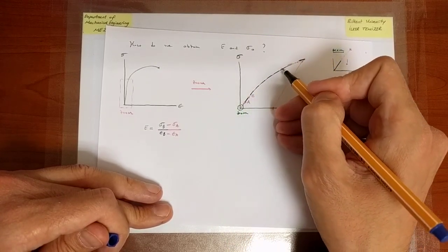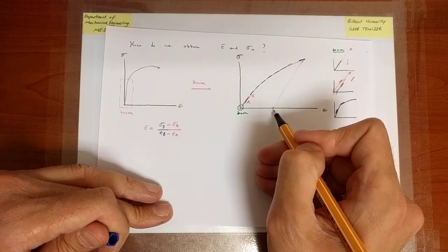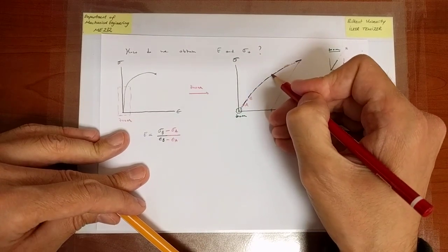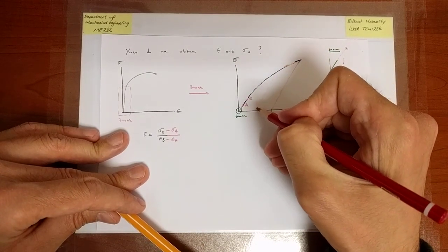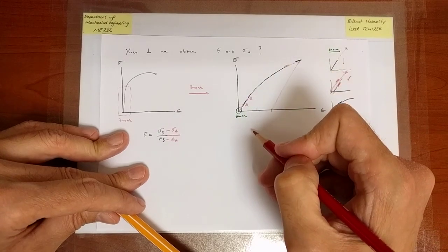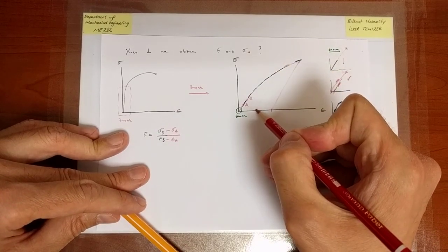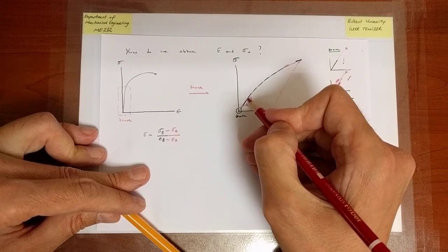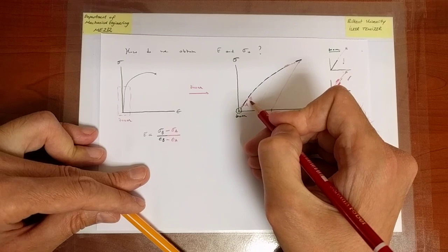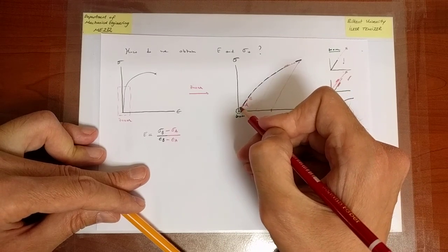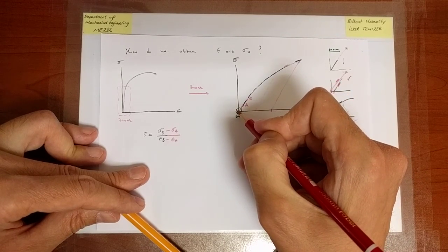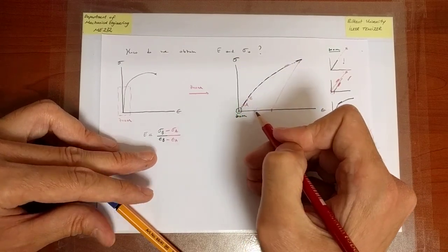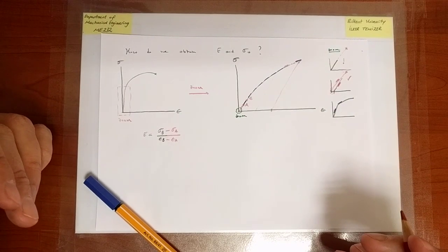So the slope decreases and the amount of plastic deformation increases, because if I were to unload at this point, the deviation in the slope is less, and also the amount of plastic deformation is less. So the amount of deviation is associated with the amount of plastic strain. If I unload in a portion where point B lies, which is in the elastic portion, or so I assume, then I will go straight back to zero stress at zero strain. There is no plastic deformation.